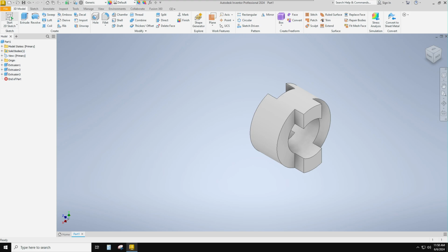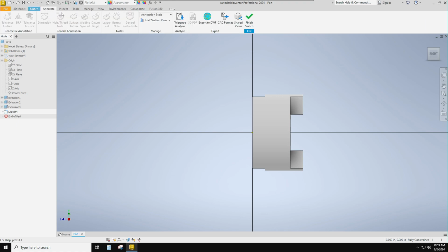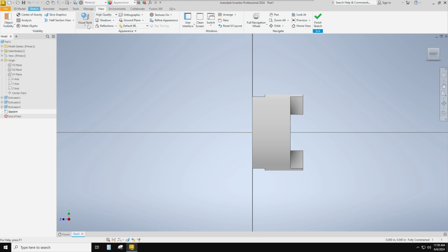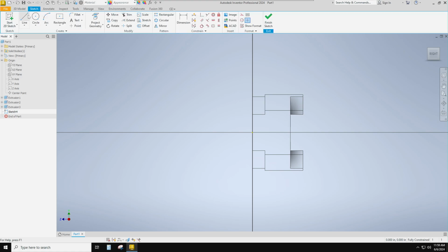So now the last thing I need is a new one, and I have to go look in this origin thing. And then I need to see this. I need to be able to see inside of it. Where's my views? So I can change that to a wireframe. So my model says, if I get onto my little sketch mode here, that 1.97 inches in, 1.97 inches in, there's a little hole.